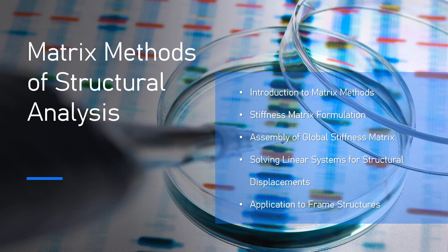3.3. Handling boundary conditions. Boundary conditions, such as fixed supports or applied displacements, must be properly incorporated into the system before solving for displacements. There are several ways to handle boundary conditions. 1. Elimination method. For fixed DOFs, where displacement is 0, remove the corresponding rows and columns from the global stiffness matrix. Similarly, set the corresponding components of the displacement vector u to 0.